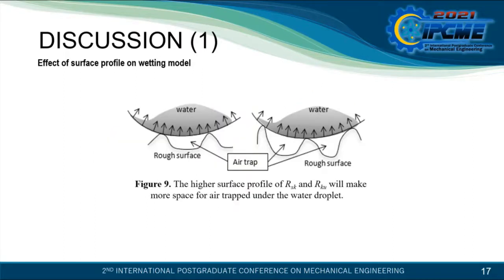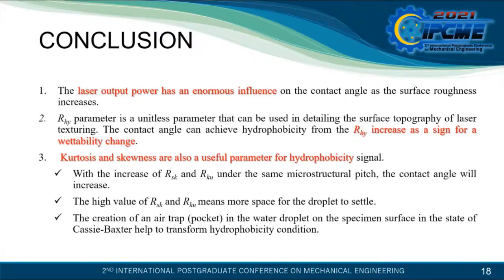Both Wenzel's and Cassie's contact angle models are closely linked to surface topography. The gaseous phase entrapment will increase the contact angle as shown in Figure 9, even if the hydrophobic surface is preferably smooth. Besides, it can be concluded that the too rough surface obtained in this work with the nanosecond pulse laser does not allow the quick reduction in the contact angle with water as expressed by Wenzel.